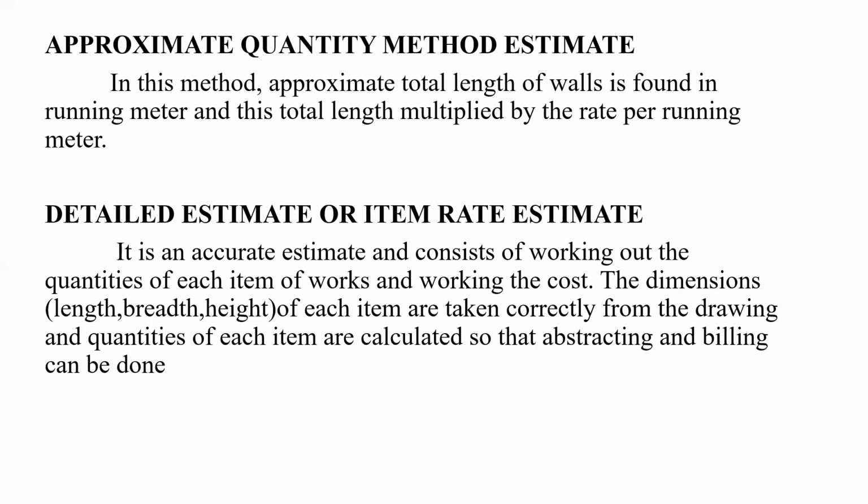And the detailed estimate is always accompanied by seven important things, that is report, general specification, detailed specifications, drawings, that is plan, elevation, sectional elevation, and regional drawings, and then calculation and designs, analysis of rates, and abstract of estimation.